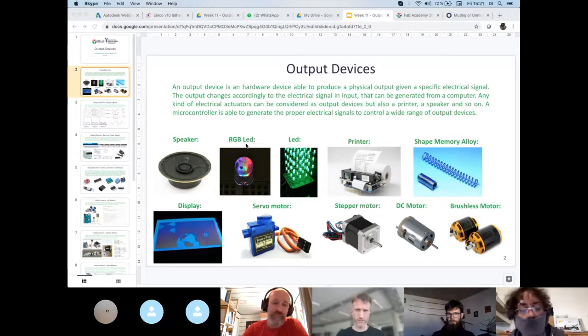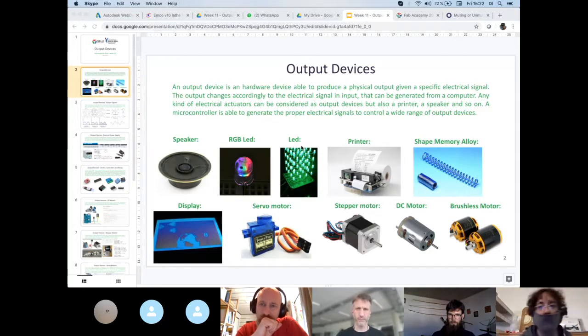Thanks. Of course, because you have three small LEDs inside, it's not that you have only two connections, like the anode and cathode of a traditional LED. You have one plus three, so four connections: three for the diodes and one common. It can be positive or negative, anode or cathode, according to the configuration.